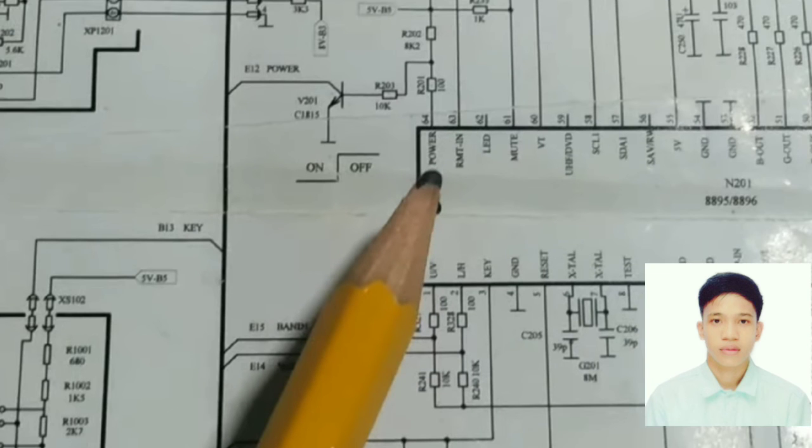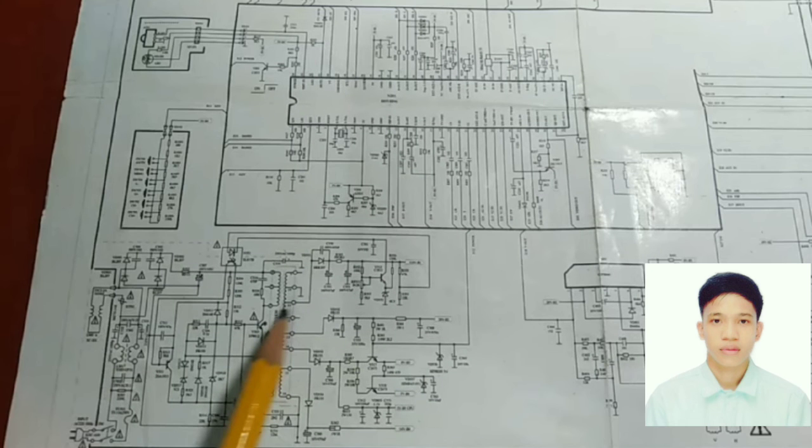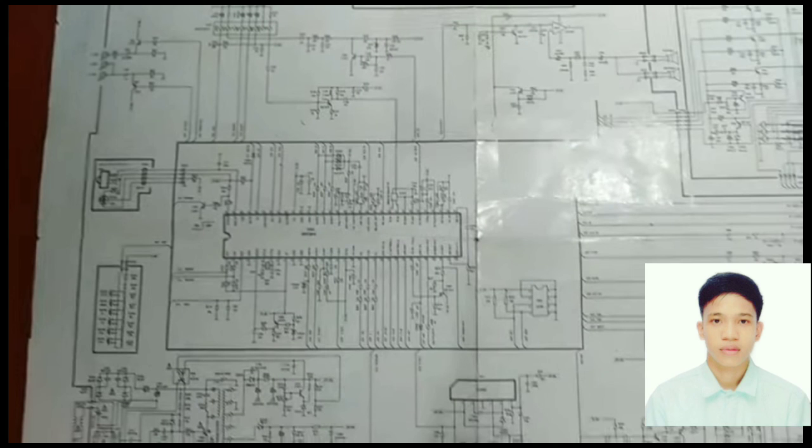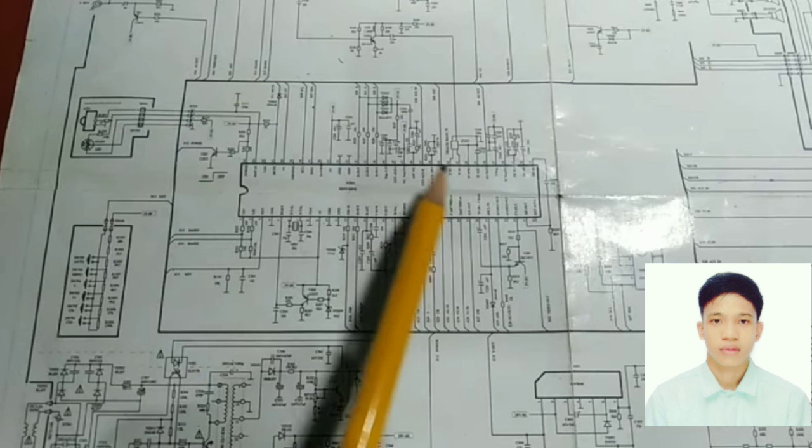And this power on, it is the one that will give a signal to operate the whole chroma system. And the operation is, there is a supply and it will distribute to all the stages of the television. After the distribution, if the chroma has a signal, it will analyze if the vertical, horizontal, tuner, audio circuit, IR sensor, drivers, and video amplifier are good. The chroma system will possibly have a chance to turn on the TV. But if there is a problem, the television will not turn on, or otherwise it will show a symbol of the problem from the particular section or circuit.